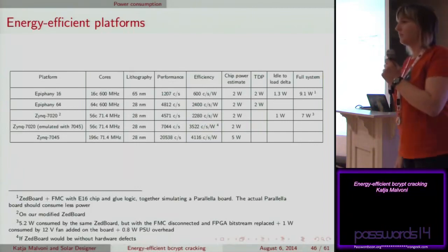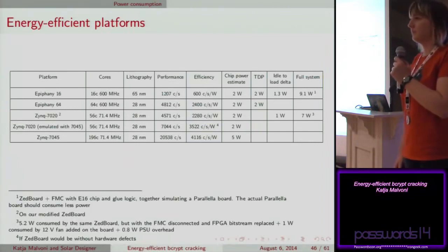So then my follow-up question is, 4 kilobytes of memory is extremely difficult to handle even in an ASIC design. It's just a lot of memory. And if that's the biggest power consumer, do you really think that an ASIC would be that much more power efficient if you had to implement 4 kilobytes of memory?